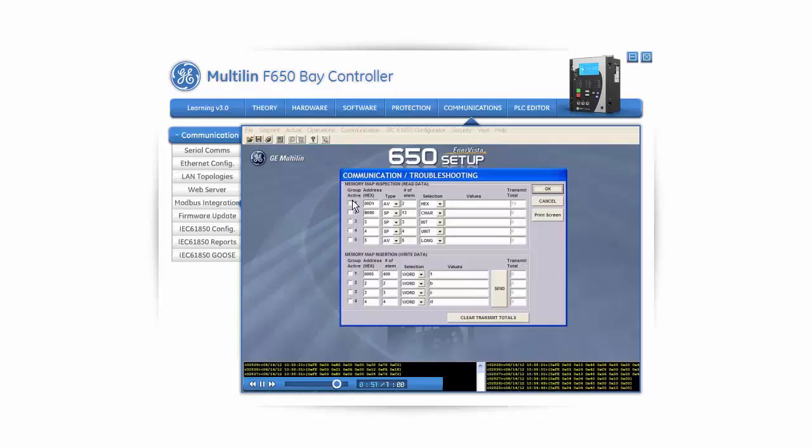First, in the leftmost column, tick the checkbox to activate the respective row. Then enter the memory address. Next, depending on which tool is being used, select from the tabs the data type and format and write down the number of elements you wish to visualize. The result will be shown in the Values column.